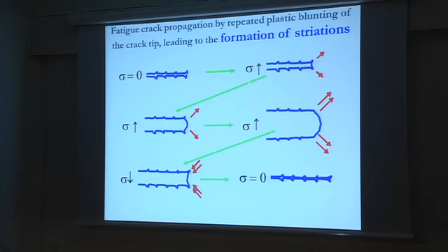Then you increase the stress, separating the two faces of the crack, then you increase the applied stress more, the front evolves, it enlarges in the direction of the crack propagation, forms a completely new front with the maximum deformation acting on this side at 45 degrees, the direction of the maximum shear stress.